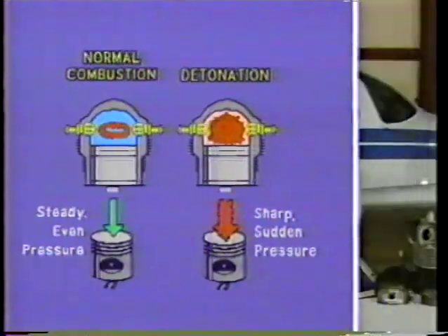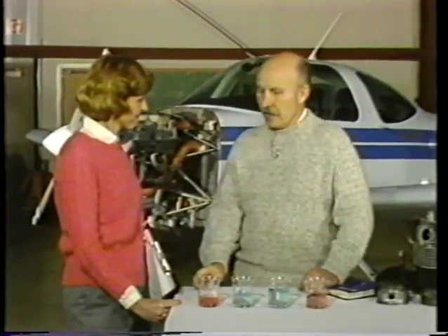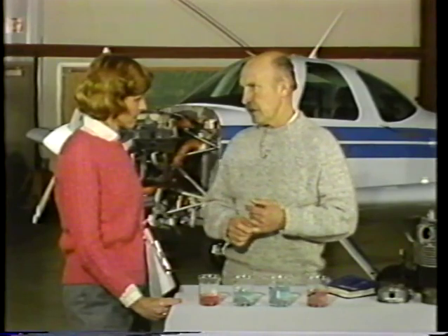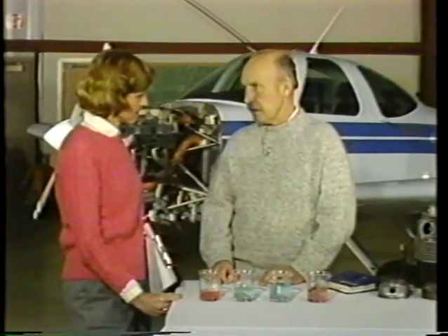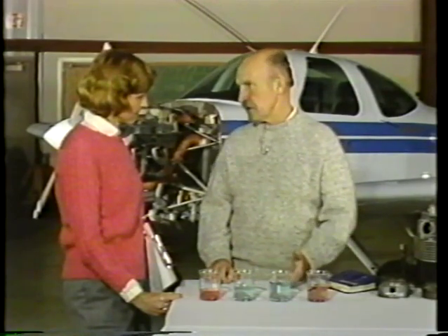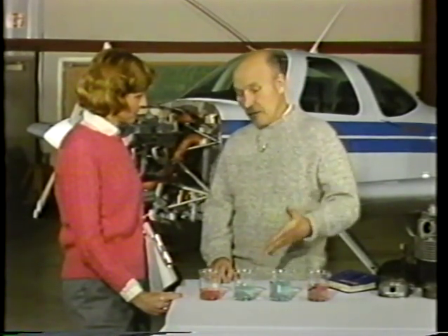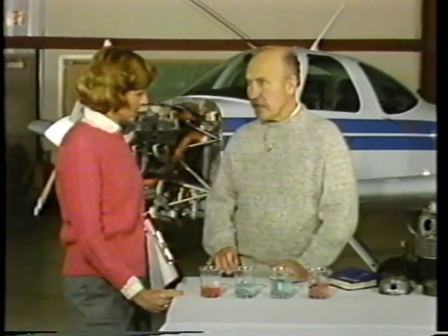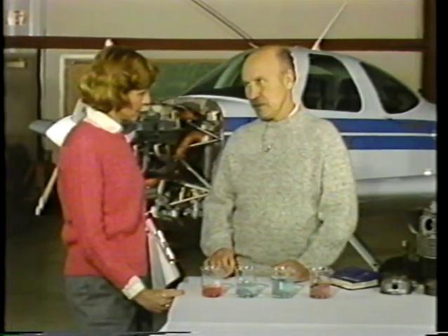In fact, in automotive engines, when you hear it ping, that's detonation. And so detonation can be caused by that. Detonation can also occur if we use automotive gas in the airplane. We should never mix automotive gas in your airplane. Besides being against the regulations, the FAA says this is not the way to do it, and it will cause a problem with detonation possibly. So do not ever mix aviation gasoline with automotive gasoline when you're going to use it in your airplane.